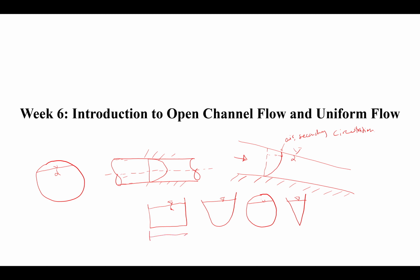This is the width of the channel, B, and this is the depth of the channel, Y. So the area is B into Y. In open channel we always consider the wetted area and wetted perimeter, P_w, sometimes represented by P only. The wetted perimeter is the addition of all these sides: B plus Y plus Y, that is, B plus 2Y.